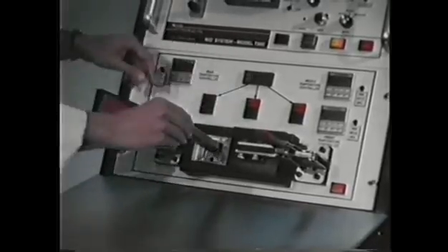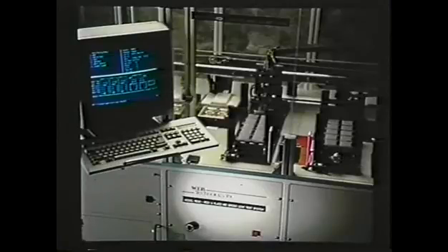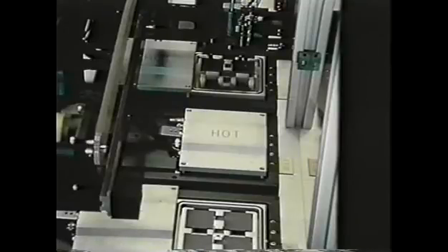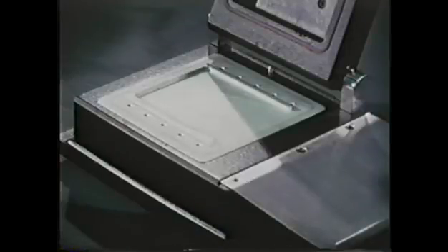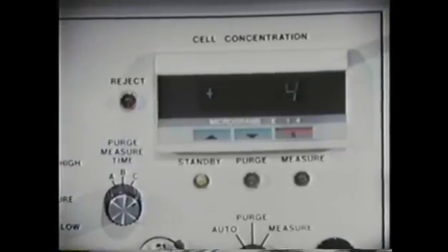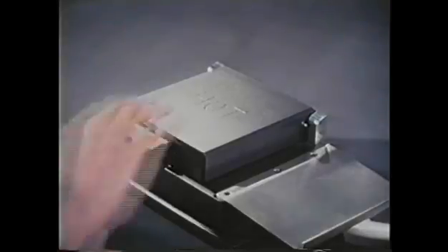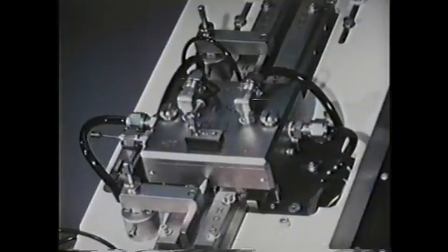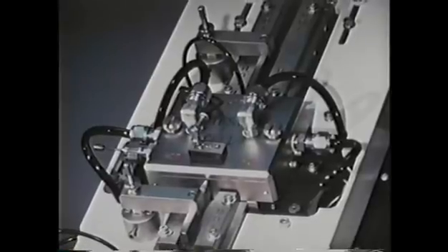High volume testing is another NID advantage, either by testing large numbers of devices in a batch or by using an automated handler to cycle devices through the test cell. If a group of devices is batch tested and the NID indicates a reject is present, the devices can be retested individually to locate the defective package. A second preconditioning step is not required per the MIL specs. Regardless of the model employed, the NID technique reduces operating costs and improves productivity. Webb can tailor a system to your exact requirements, taking into account the required throughput, desired degree of automation, cost, and other factors unique to your needs.